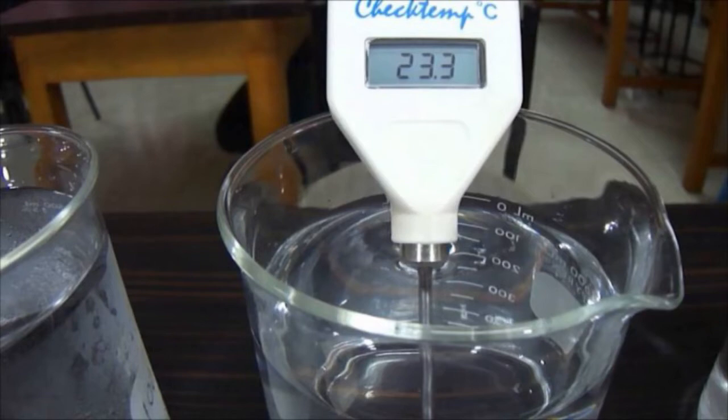This first part consists of first heating 1 liter of water on the electric grill to 60 degrees. While the water is heating up, install the heat exchanger system as shown in the lab report. Then we need to measure the flow of water in the inner tube. For this, we measure with the graduated cylinder the volume of water that comes out of the inner tube for 10 seconds, and later we calculate the flow in milliliters per second.